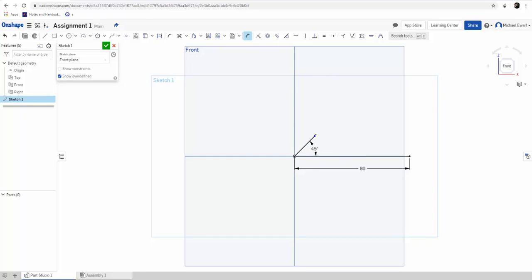And then we're also going to click the 2 end points. We want to make sure we're not doing the sideways one, or that angled one. We want to go just left and right, which was 10 across. Okay. We're going to click the line tool again, and starting there, we're going to go up. One thing I do like about OnShape is that it's a little bit more clear when we're going straight vertically and clicking on lines.